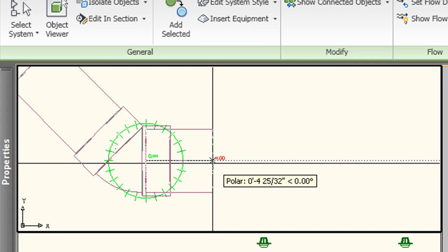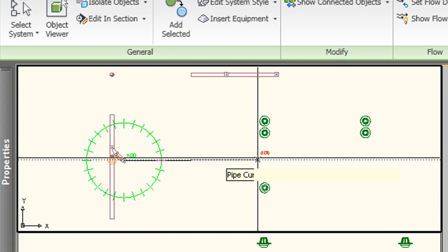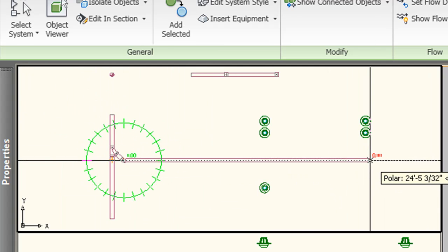You can also set angle of deflection, so how much bend can you get at an actual connection point, like in real life, 3 degrees, 13 degrees, whether it's PVC or hub piping. And then what you would expect to do next is to come out here and actually pick my terminal connection point. Where am I going to end this pipe? But in AutoCAD MEP, that's not the best practice.